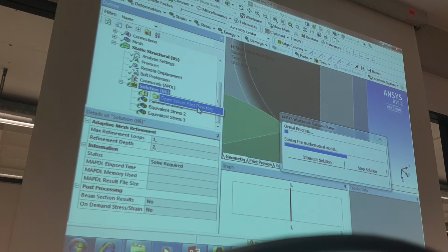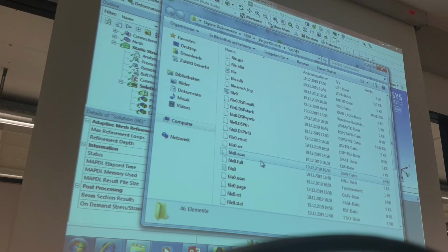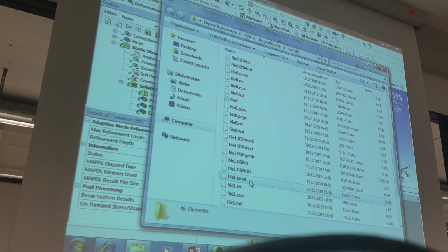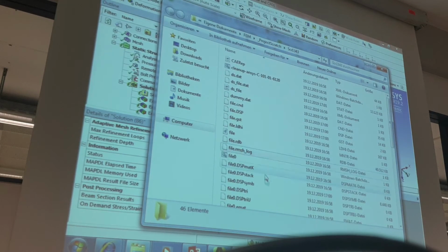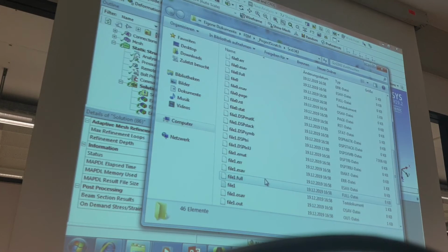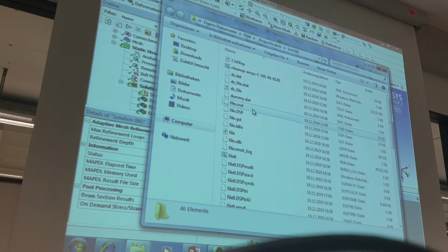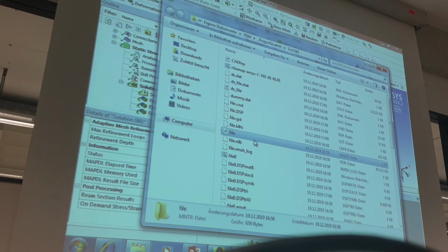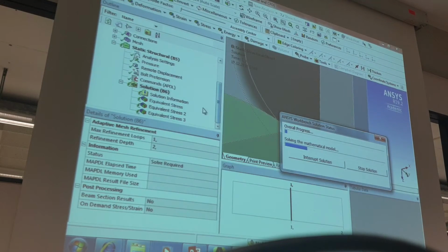But with 60,000 also, normally direct is better. And with this strategy, we can save a lot of time. So we can check this monitor file to see whether the first time step was quick or not. File monitor here. Okay, but I don't know how long it was in the other simulation.